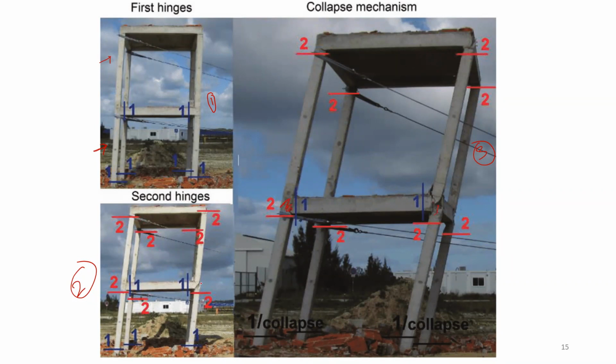Here you can see very carefully in the second figure, mild cracks happening on the member. And even if you try to increase heavy amounts of load, then the structure will collapse. That means whatever moment is there in the compression zone will shift to the tensile zone, and whatever moment is there in the tensile zone will shift to the compression zone. When these moments shift their places, the collapse of the structure will take place. So initially, wherever the plastic hinges are formed, at that place the structure will fail. So that is what the plastic hinge formation and plastic moment formation are.